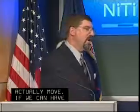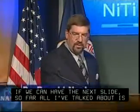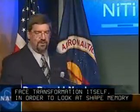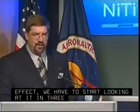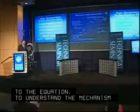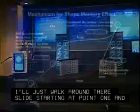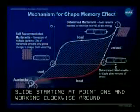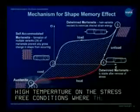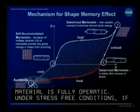So far, all I've talked about is the effect of temperature on the phase transformation itself, but in order to look at the shape memory effect, we have to start looking at it in 3 dimensions. We have to add stress and strain to the equation. And so in order to understand the mechanism behind the shape memory effect, I'll just walk around this slide starting at point 1 and working clockwise around the figure. If we start at point 1, we're at some high temperature under stress-free conditions where the material is fully austenitic. Under those stress-free conditions, if we allow the material to cool, will form what's called self-accommodated martensite.